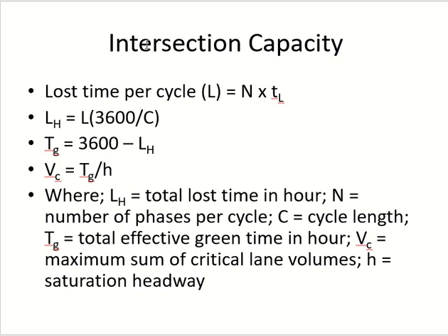So it's called one signal. For us, as per the design, it's one signal, because all traffic lights are operating on the same cycle length. They are not independent. This building has a structure, and this structure is connected, so you cannot take one floor at a time. But when you are designing, you will design the entire building. Same thing here. On the field, it looks like 4 signals, but they are not 4 signals for us because we are designing it as one unit. So cycle length is for all. When I said all directions, it means all signals.